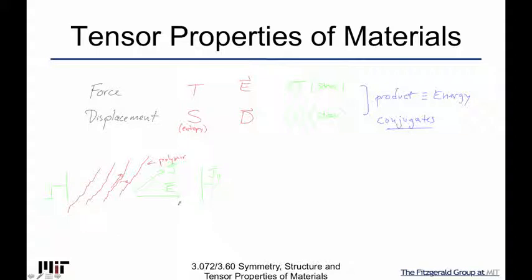And after we develop some of our tensor foundation, this is one of the things that I actually want to get to in the class, because it's a very practical thing. You kind of make a slice of a material. For some reason, it's always in a particular orientation, and other things can be at angles to it, but you actually measure properties in one dimension with one particular force. And so this is really one of the main, very useful properties of tensors, which is to relate such an experimental situation to what's happening inside the crystal with a reference frame that we know inside the crystal.